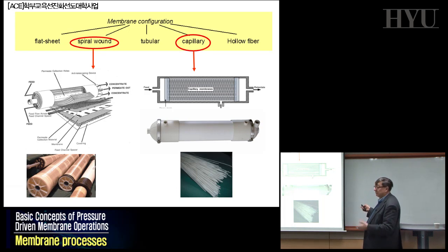In this case, a huge membrane surface is available, and if you control correctly the flow dynamics, this can be quite interesting. But for using this, you must be sure that you don't plug the system. The pre-treatment has to be very effective. The chemicals have to be not polluting, not adsorbing on the surface, etc. If you are using this one when it's possible, it's okay. If you use this one when it's not possible, shortly, after a few months you destroy the system, you have to start again.